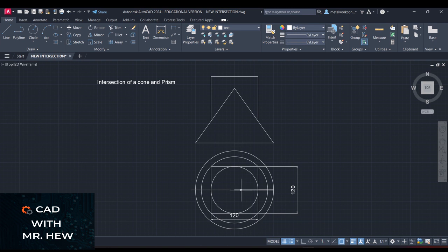All right. So what we're going to do now, we're going to draw a line from this intersection of this line, which would represent the center line when we're finished, in this circle. Intersect this horizontal. We're going to project a line up to the side of the cone and draw it across, and that will be the largest disk.